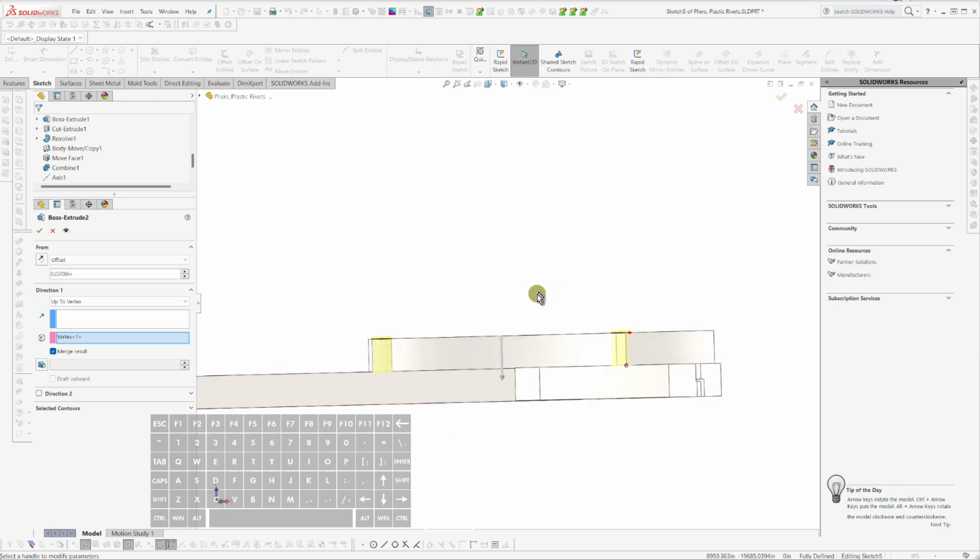for print and place hinge type stuff and supports. It breaks apart pretty easily if you do 0.02, I find, especially with PLA. I need to flip the offset. Oh, yeah, I was thinking about that wrong.